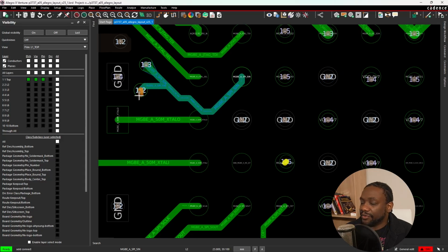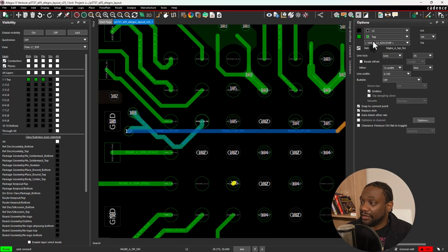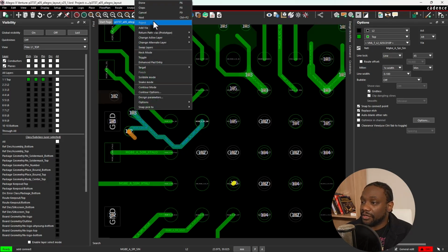And the via I add would be layer 1 to 2. Okay, I don't have to go all the way down to layer 10 just to make my connections. And looking at my options here, I got 2 different types of vias I could do. I could do layer 2 to layer 7, depending, but yeah, layer 1 to 2 is the best because that's the type of via that's allowed on this trace or signal.